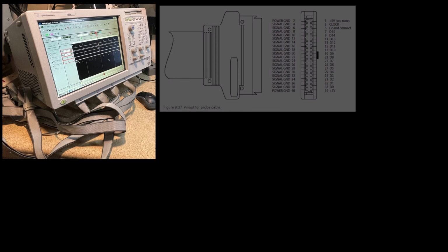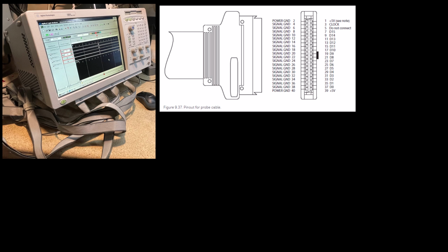Now, these logic analyzers all basically connect the same way. They have ribbon cables that connect into basically a capture device in whatever chassis you're using, the 1680A or the 1690. And they have a 60-pin high-density type of connector that connects into the chassis. And then on the other end, there is a pair of 40-pin connectors. And so that's what comes out of all these ribbon cables. And if you can see it on this picture on the left, it's labeled down on the bottom, pod 1, 2, 3, 4, 5, 6, 7, 8. So I have these 4 pod cables, and these cables go to the back of it, plug in with one of these high-density 60 pins, and then it comes out and basically splits into a pair of these 40 pins.